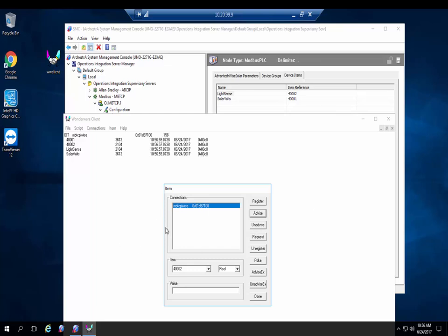So once we've proven that we can connect to the WISE module wirelessly to our field devices and bring it into the Wonderware system using SuiteLink and test it out with the Wonderware client, then any other Wonderware piece of software should be able to connect to these devices and display that information, whether it's in InTouch. So you would do the same type of configuration that we did in the WW client. You would point to the device group and the item name, either through the register number or the actual alias table, and bring that data into InTouch or the Wonderware historian.